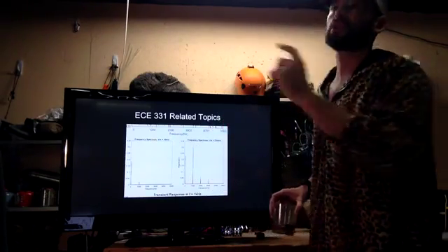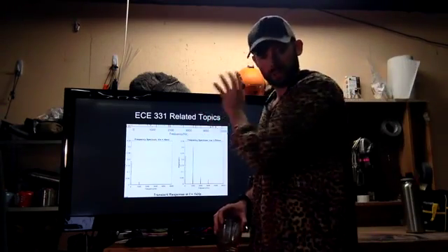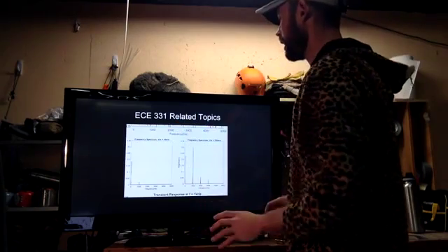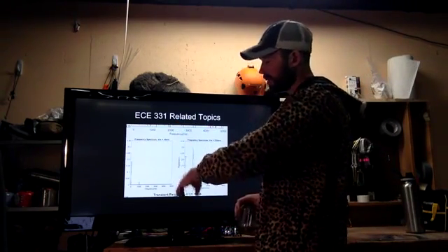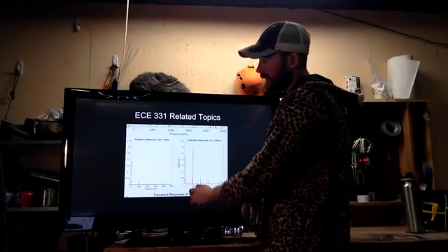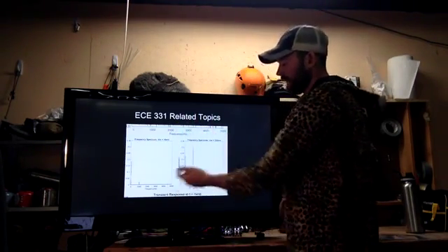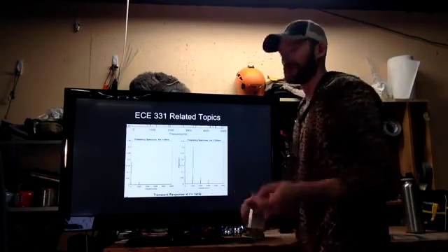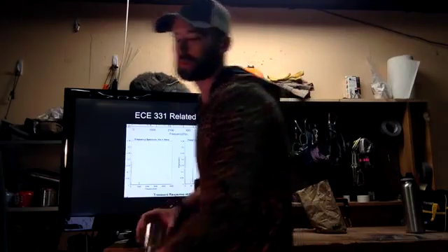That's the x squared and the x cubed elements of the Taylor series for the input. The magnitude of the DC input goes up, and the magnitude of the 1K dramatically increases, but we also have noise and distortion at multiple frequencies, which actually degrades the quality of the system in some cases.